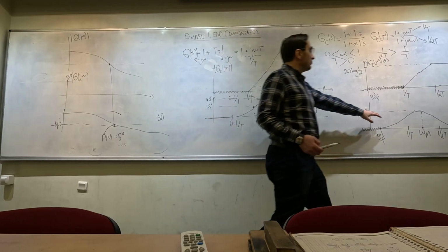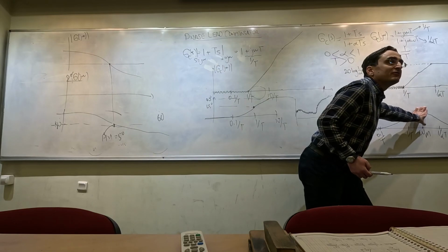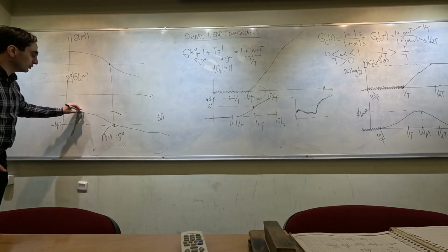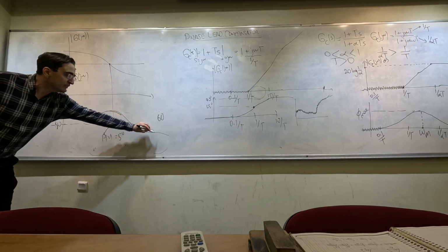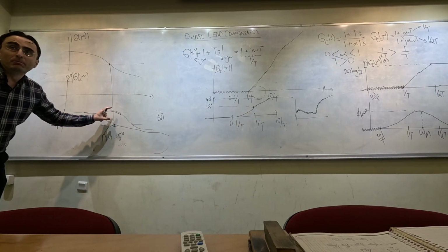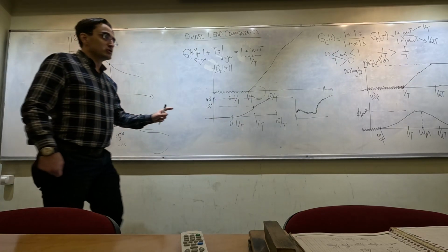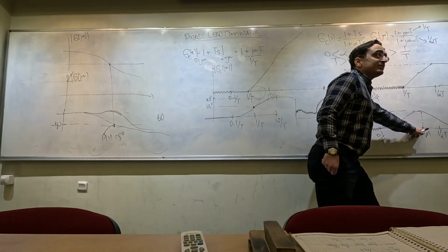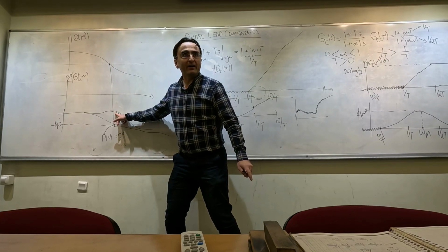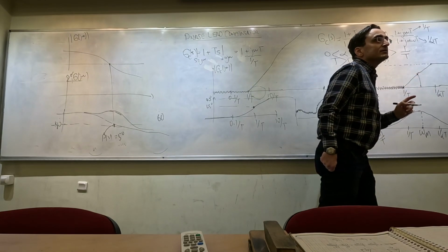I'm going to benefit from this compensator by placing this peak phase lead around the gain crossover frequency of the system. So I'm going to try to add that into this one to get a large phase margin for the closed loop system. But unfortunately, there is a side effect here. When I add this phase, somewhere around here, peak phase, unfortunately this positive magnitude is also going to be added into the system.